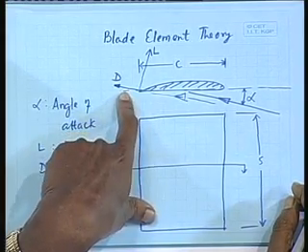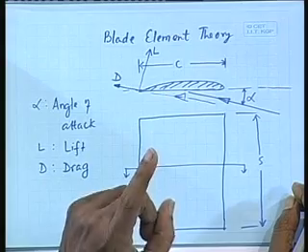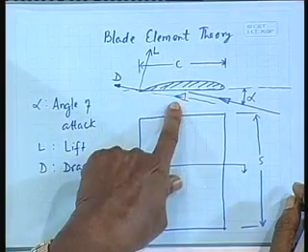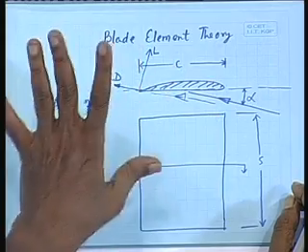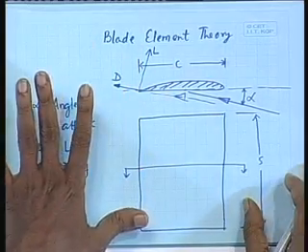Now, this drag, remember we are talking about inviscid fluid, that is no viscosity. This drag would be there due to action of the flow itself without considering viscosity. This is called induced drag. Okay. This will be further increased due to viscosity, but at this moment we are ignoring viscosity. Okay. So, we have this for a span.